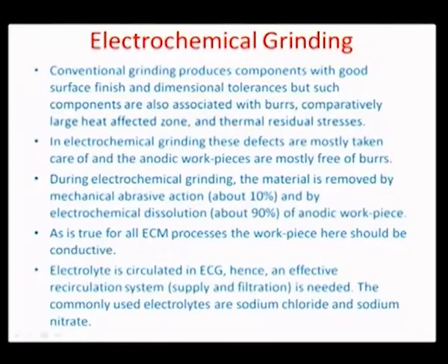The next example that I would like to consider is another corollary, or an extension, of electrochemical machining, and it is called ECG, or electrochemical grinding. And let me just recall a little bit about what conventional grinding typically does. Conventional grinding is a very fine machining process, which in general produces a superior surface finish of the components.